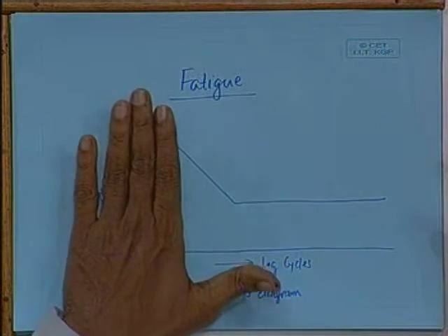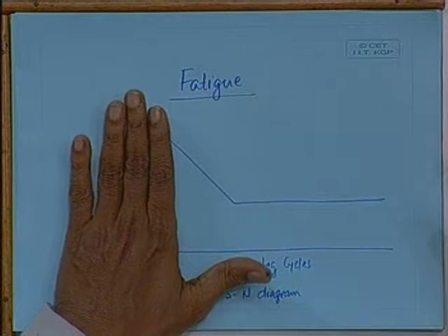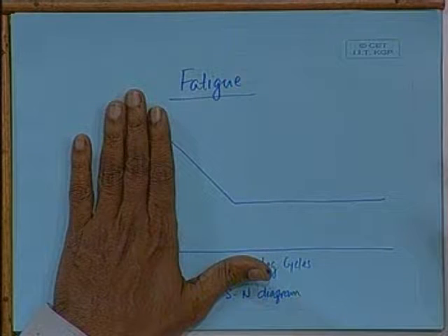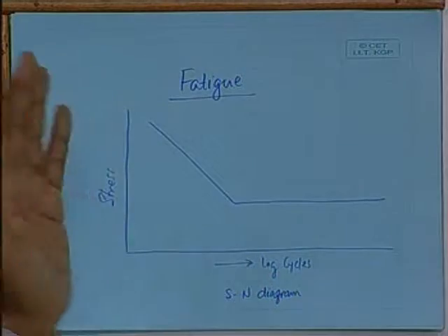What happens in case of ships? Are we talking low cycle or high cycle? Normally, for the main ship structure, stress levels are high, so it will normally withstand low cycles. Therefore, it has normally been found that for an average ship which does not have much variation in loading patterns, a 20-year life cycle is good enough for the normal metal to withstand fatigue.